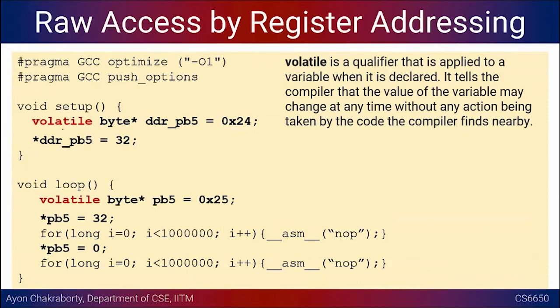Please note that while we operate on memory, it's a good practice to use this modifier or qualifier volatile whenever we declare a variable, because there could be many operations in the hardware that are changing the value, and we don't want the compiler to take any decisions on its own, whether to update that particular variable or not. Whatever updates come to that particular variable, we have to write that, right?